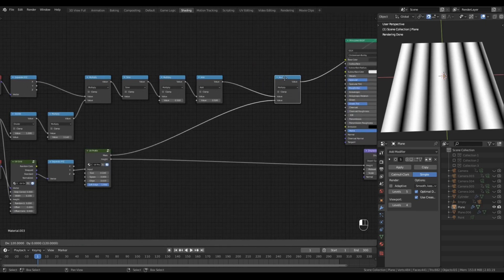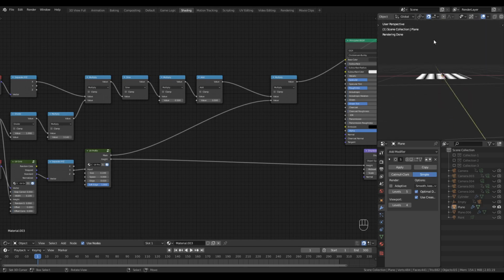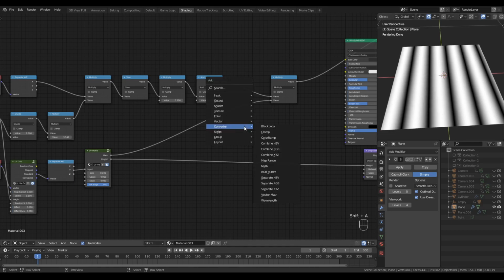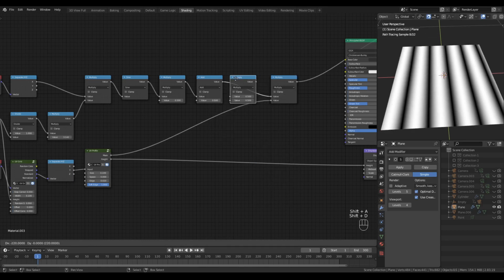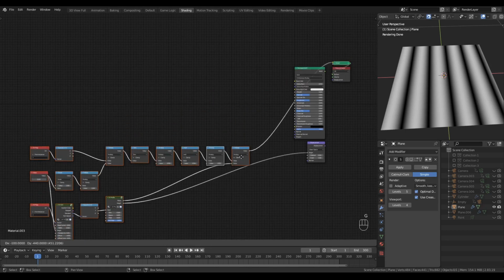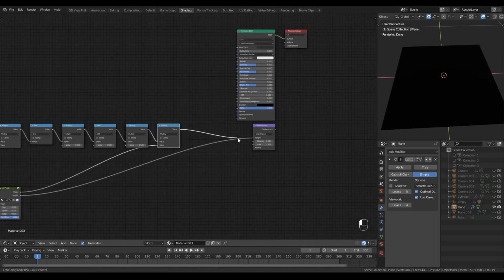We should also introduce some height control for this setup, because this will give us 0 to 1 displacement, being way too large for our needs, certainly for this example. I'll drop in another math node. Actually, no, I'll duplicate this one. And let's get a better idea of the displacement that we're getting by using an actual displacement preview.